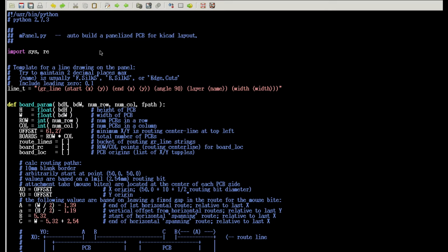Since then, I found a smaller version, which is the SK6812 Mini, or it might be called the Mini 3535, depending on where you look. And they're 3.5 millimeters square, whereas the WS2812 is 5 millimeters square. So I had to start again, redo all the footprints, redo all the PC board layouts, and redo all the panelization. Well, I didn't want to do the panelization again.